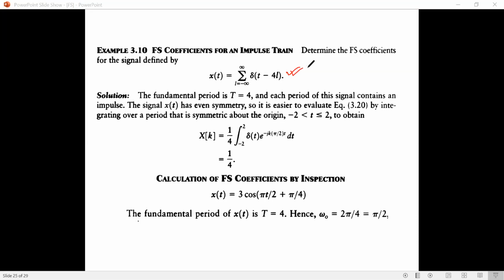a continuous time impulse train, and let us analyze how it behaves in the frequency domain. Okay, is it not a periodic signal? Because if we plot it for each value of l, you will see that for l equal to 0 you have an impulse, but a difference is there between your continuous impulse and discrete impulse. Because the continuous impulse has magnitude equal to what? 1? For the continuous case? No, sir. Infinite, sir. Infinite, yes. Discrete case is 1, yes.